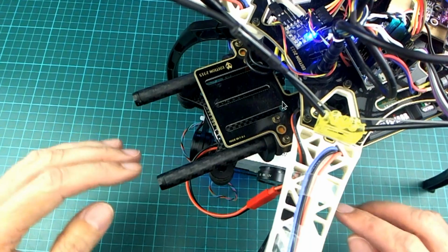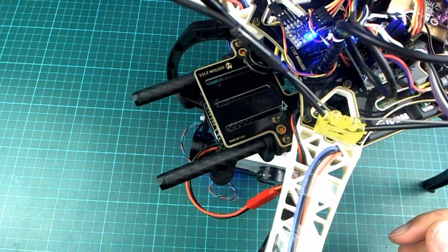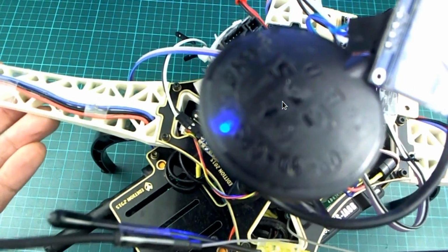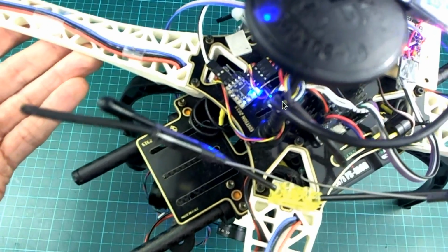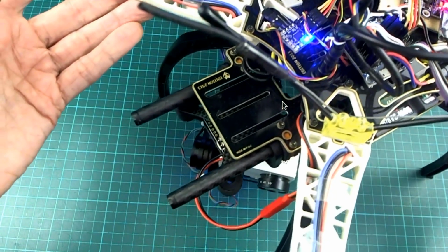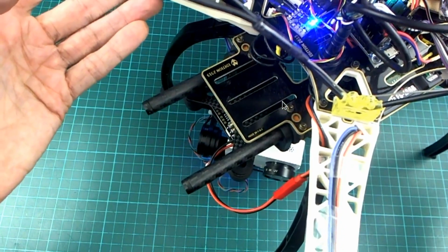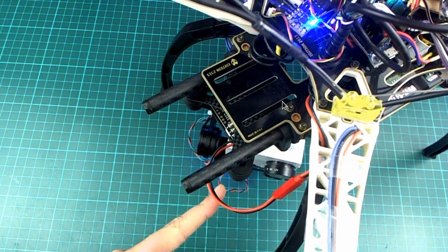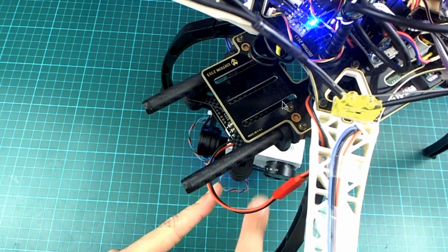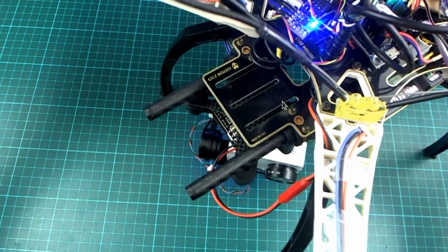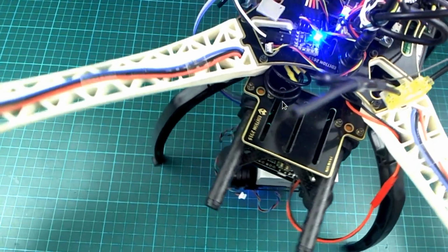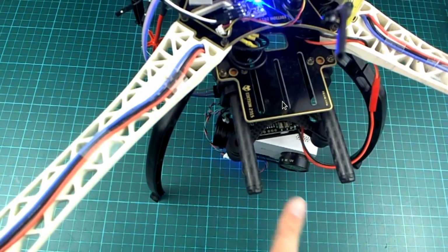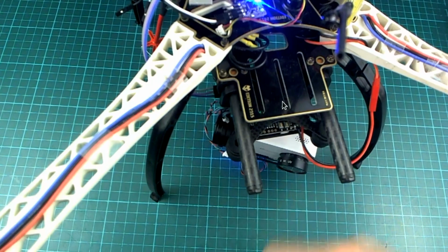It's not going to work very well at the moment because the quad is indoors, and like I say, this GPS module, being an M8N, is quite a good one, so it does actually pick up a decent GPS signal even inside, but it's not going to be very accurate. So at the moment the follow me tag is more like over this direction, not that direction. But the point is that as you move the quadcopter around, the camera should maintain the same direction. So it's pointing pretty much directly towards me at the moment.